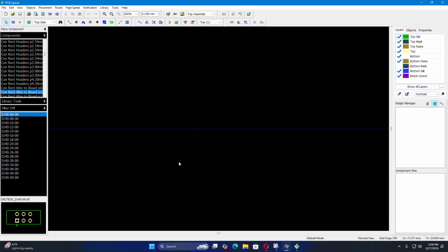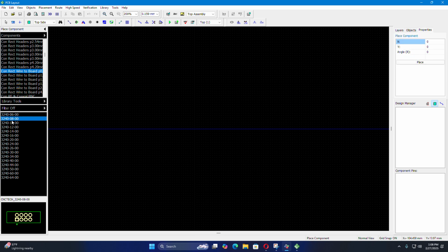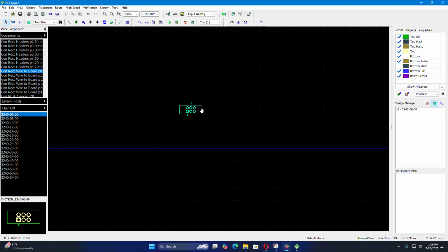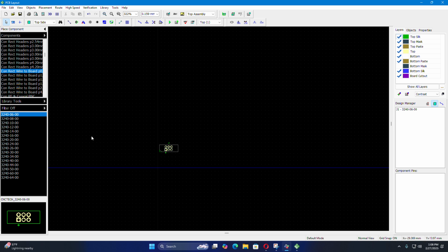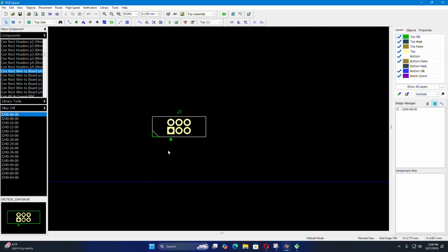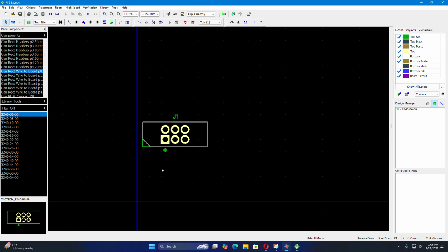This is the PCB menu or the page. Here all the components are available, the same. So you see the component, I think we used the same one in the schematic. So here you see this is the PCB footprint. So if we want to use a component which is not available in this built-in library of DipTrace, then we will have to design our own custom footprint and schematic symbol for the component.